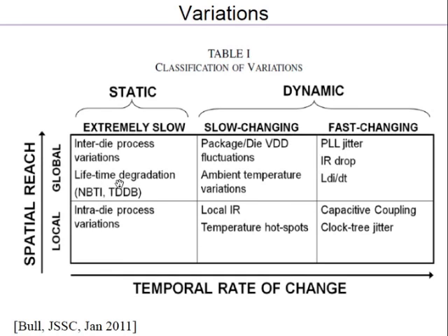You also have changes when you make a chip. The chip runs at a certain speed now, but after 5 years it will run at a slightly different speed. It ages, and maybe the oxide slowly starts degrading, maybe certain charges get buried because you are operating at high voltages. So slowly you have some charges embedded in the oxide.